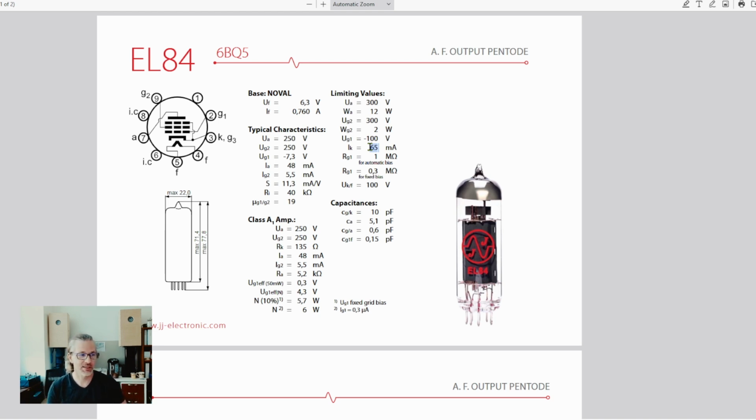If you design it and all of these values are this much or a little less, then your tube will operate optimally and have the life expectancy that's provided on the datasheet. If you put any or all three of these values much lower than specified here, then your vacuum tube's life expectancy is going to be exponentially longer at the cost of exponentially less power output.